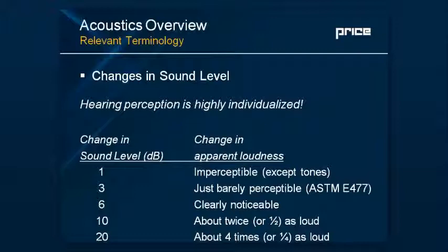A lot of times, it's important to realize where you are when you're designing a building versus when you're actually going to bid or install the equipment. A lot of times that equipment changes, and unfortunately, in many cases, it's not even available. So it's important to check the noise levels and make sure they have not, in fact, changed. I know a lot of times I would see equipment increase the noise level by as much as 8 or 9 decibels, and that will be perceived as being twice as loud, so it definitely requires some additional review.